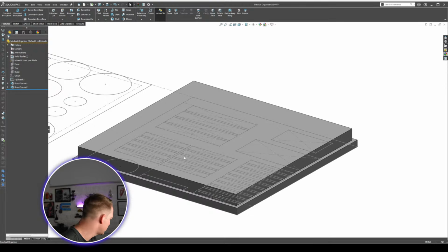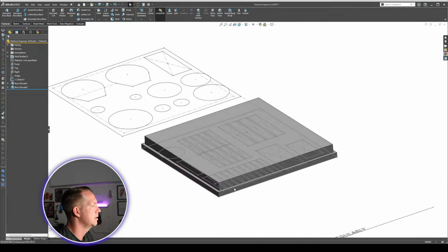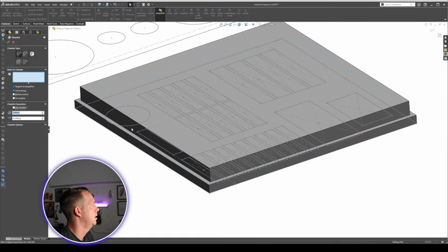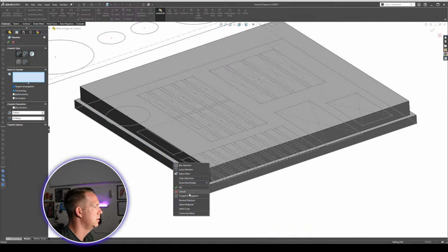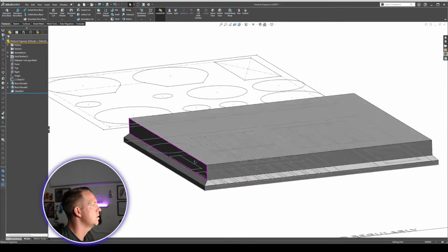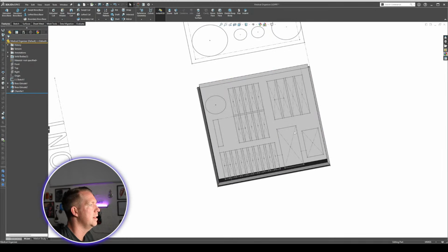So wherever we do these slots, I don't want you to put it in the slot and the whole thing just falls over straight away. So it kind of needs to come up with a bit of height. At the same time, I want to do something a bit neat on the outside. I was thinking a chamfer around these edges. So chamfer up to a square and then some areas cut out.